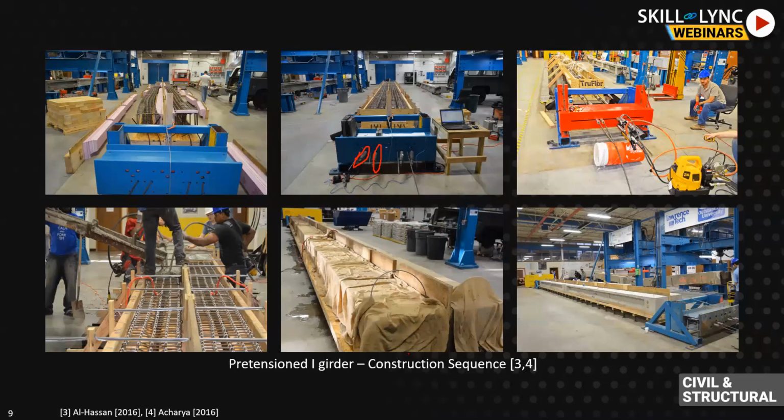So what will happen if we break those strands? This bed was holding that strand with some force. If we cut those strands, they will be free at the end right here, and this force will be transferred to the concrete structure, and that is exactly what the prestress force is. There are a couple of terminologies involved here. We'll go through them, but I think in this picture we can probably talk about that.